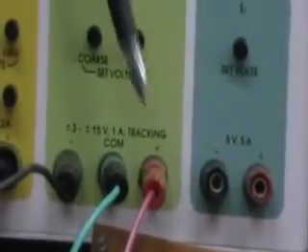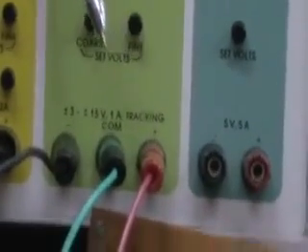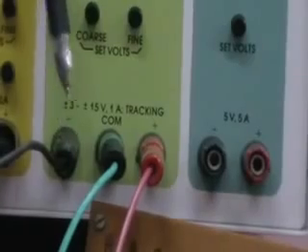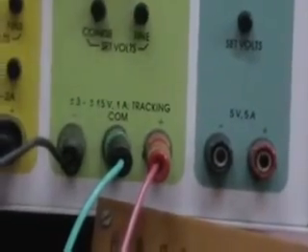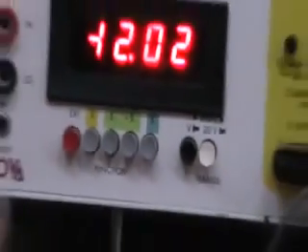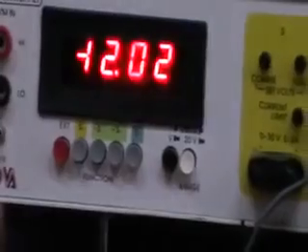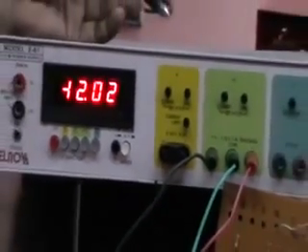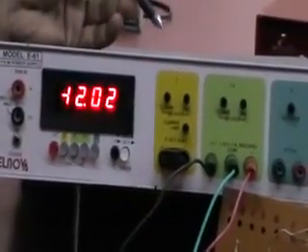The red wire indicates the plus 12 volts, the black wire indicates the minus 12 volts, and the green wire indicates the common ground. You can see these variations by pressing the plus S2 and minus S2 switches there. And we can make the variation by using the coarse and fine knobs, setting the plus 12 and minus 12 volts. So we will give the inputs to the differential amplifiers.